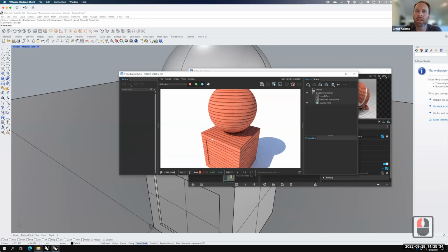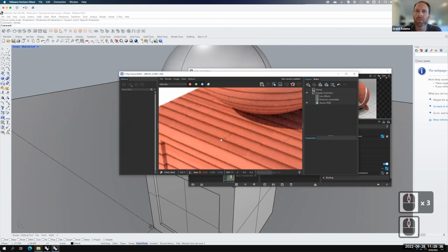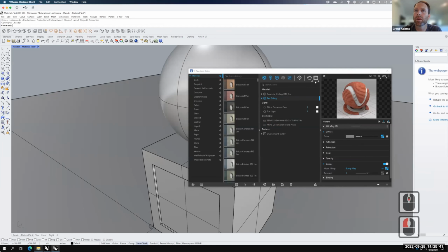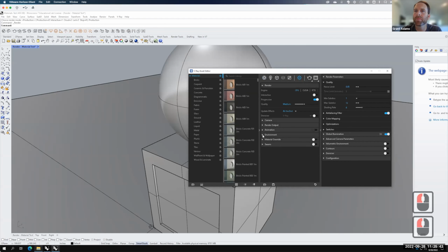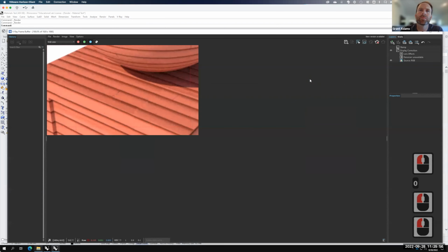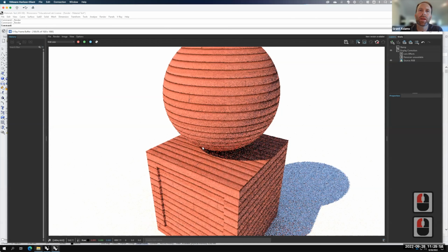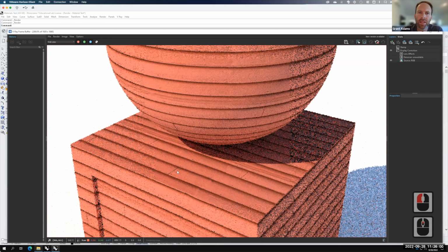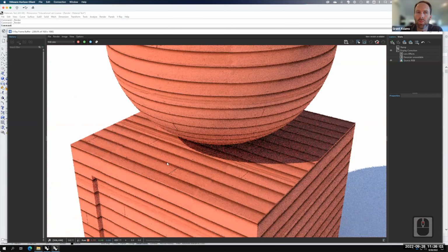And we can see that we're starting to get some texture on the surfaces. I should probably up the size of the rendering here. Let me go into my V-Ray settings, and we're going to go to my render output, and I'm just going to bump this up. We'll say maybe this is 1080. Oops, left out a 0 in there. And so now if I were to render it, we'll probably get a little bit higher level of detail, but we can see the texture starting to apply to the boards themselves. Which is good.